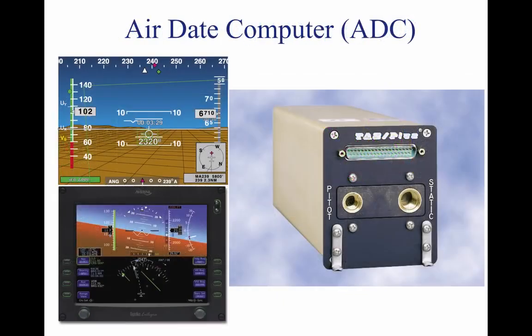Individual panel displays are able to be configured for a variety of aircraft simply by installing different software packages. Manufacturers are also able to upgrade existing instrument displays in a similar manner, eliminating the need to replace individual gauges in order to upgrade. Electronic flight displays utilize the same type of instrument inputs as traditional analog gauges. However, the processing system is different.